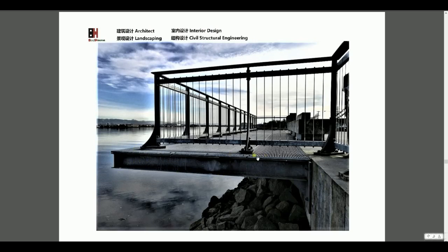So 10 feet is a 3 meter projection. For wood construction cantilever, the limit is 4 feet, so 10 feet is too much. So we should take a steel cantilever beam to take care of this kind of decking.